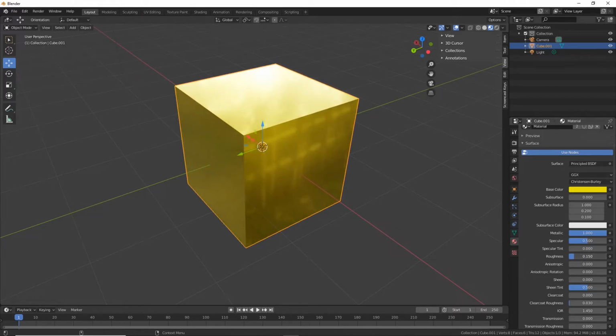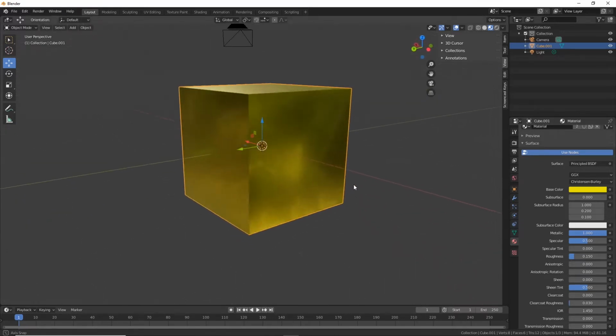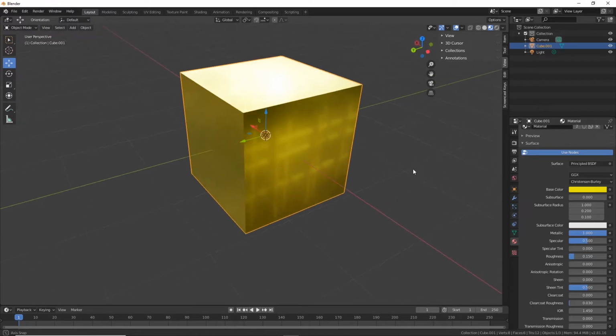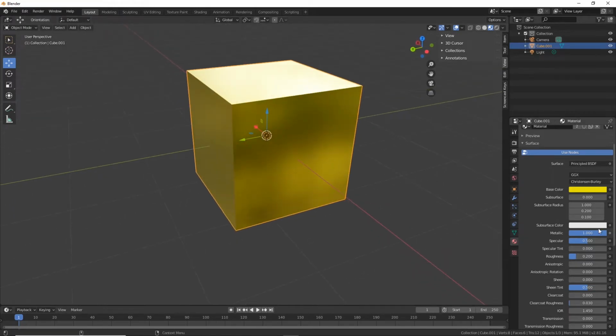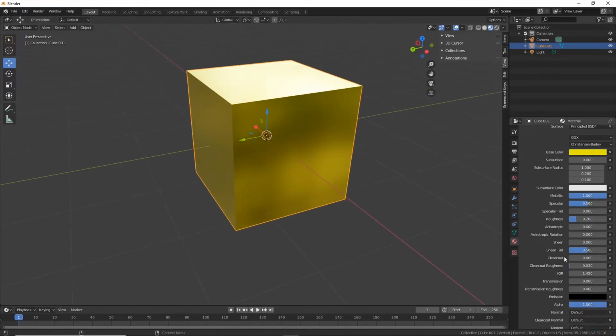So if I wanted to make it kind of a rough, kind of a metallic, reflective, opaque, I'd go maybe 0.2 on the roughness and give it full metallic. There is no such thing as half metallic. So really technically this should be like a toggle. You can fake materials, I guess, with this, but something's either metallic or it's not. So if you're going to make something metallic, crank this all the way up.